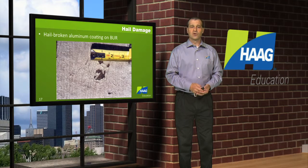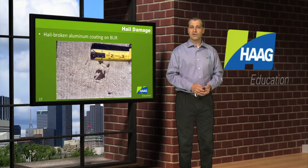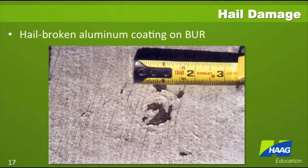This photograph shows a close-up of concentric circular fractures on an aluminum-coated roof. Some of the coating actually spalled away, exposing the dark black surface underneath. If the damage is limited to the coating, then the roof surface can be cleaned and recoated.